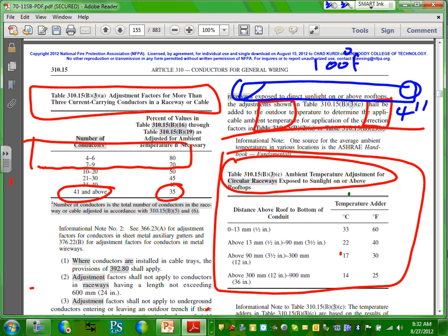Because I put them on the roof this way, these conduits will be cooked in 2 ways. One, direct sun rays on it. That's where the 100 Fahrenheit ambient temperature comes into play. And two, reflected heat from the roof. That's where this table comes in. Okay, so it's 4 inches. If you look, this is from 1/2 inch to 3 inch, and this is from 3.5 to 4. So we're right here. Everybody can see that's the height that you're at.